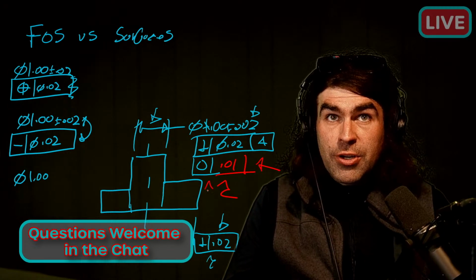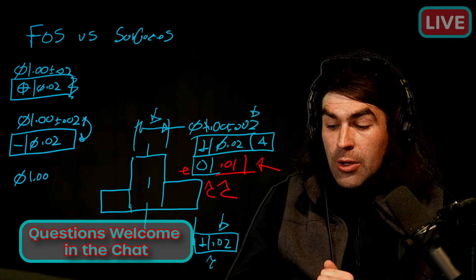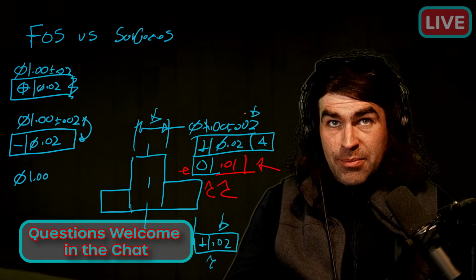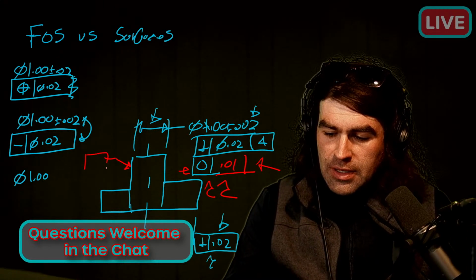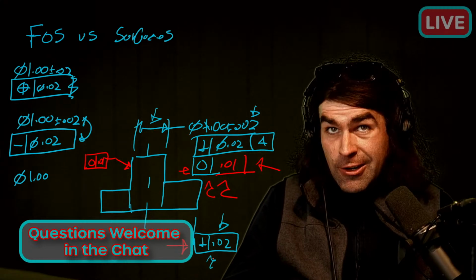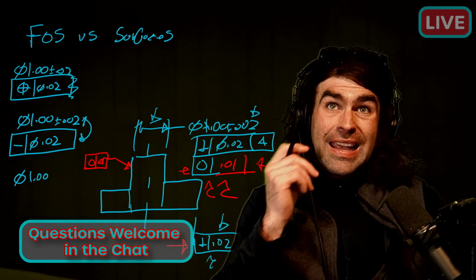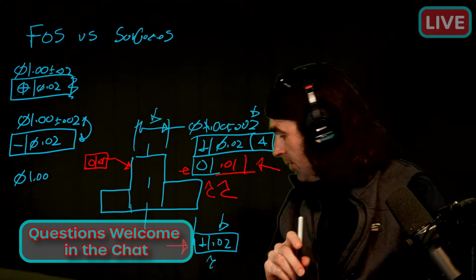But because this circularity applies to a surface and not the axis, we really don't want to put it with the feature control frame, with the dimension. What we would like to do is lead or direct it, just like this perpendicularity down here. Same thing with cylindricity.